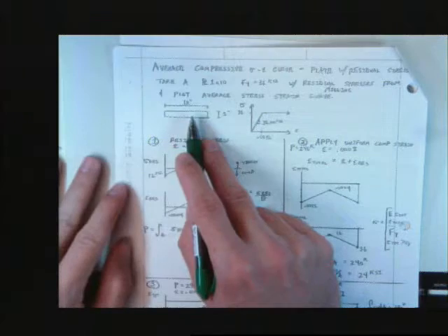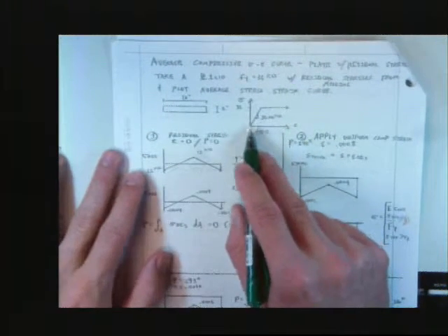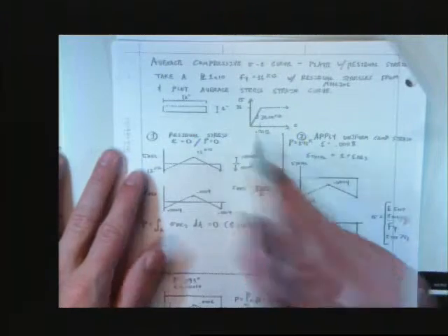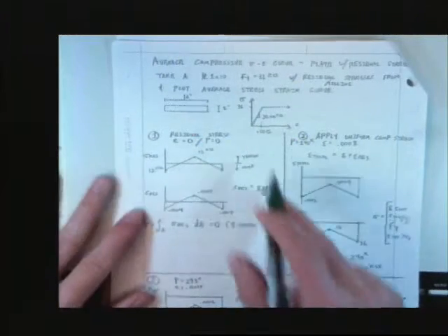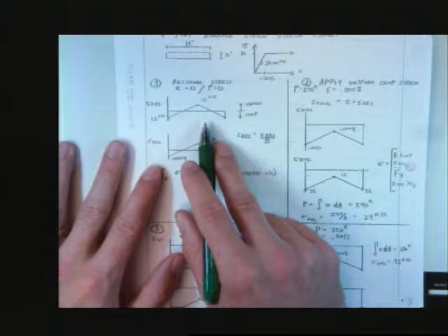So let's start out with just a very typical steel plate, and we're going to take it through this stress-strain curve. Ugh, this is typical. We know this. This is boring. Oh, we're going to add something to it. This plate's going to have some residual stresses in it because of the cooling process.